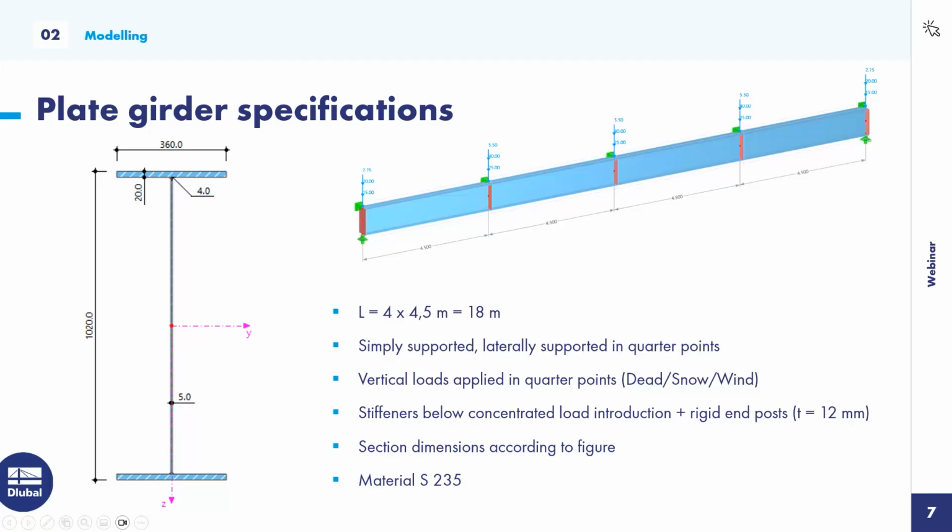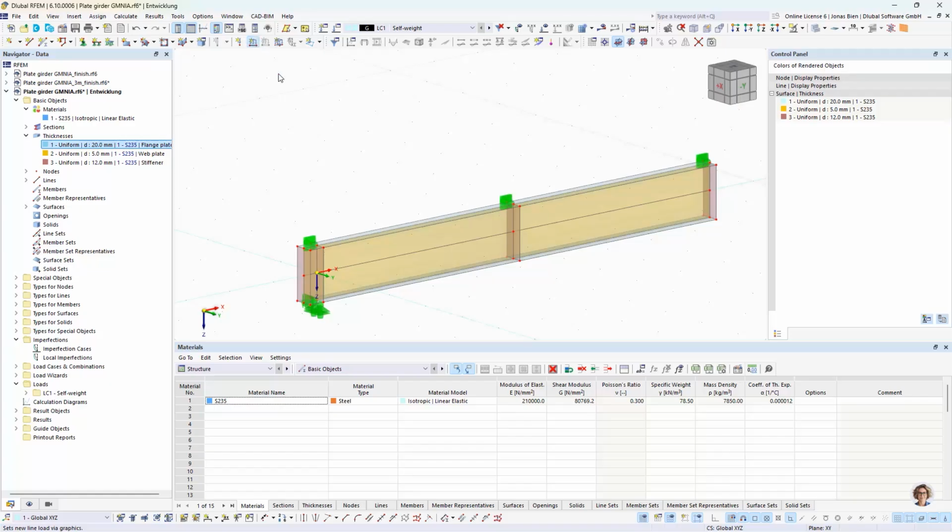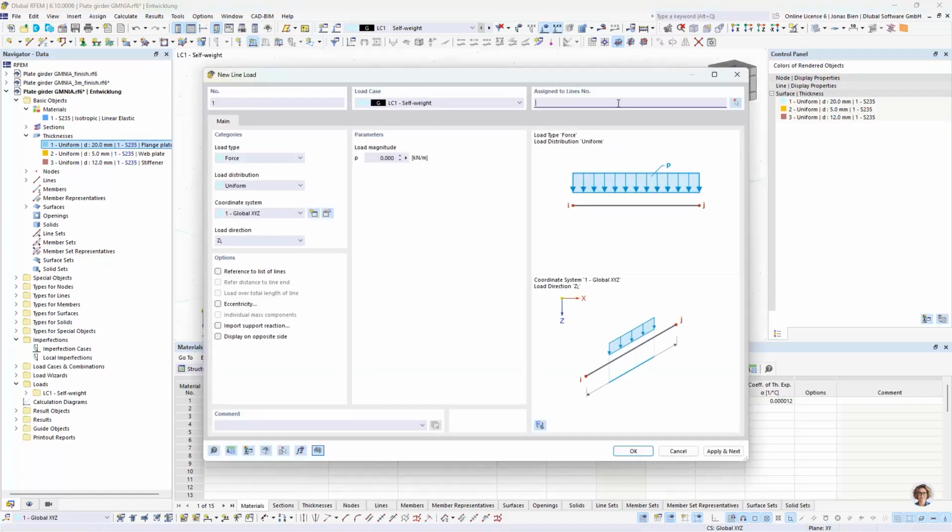So these I want to define separately for those 3 load cases. So let's start with the definition of the, or maybe we start with the definition of the dead load here in the first case. So let's do that. I want to apply those loads as line loads, also again to avoid singularities when using nodal loads. And I could now go along or start with calculating my equivalent line load for a concentrated load of, for example, 15 kilonewtons by hand.